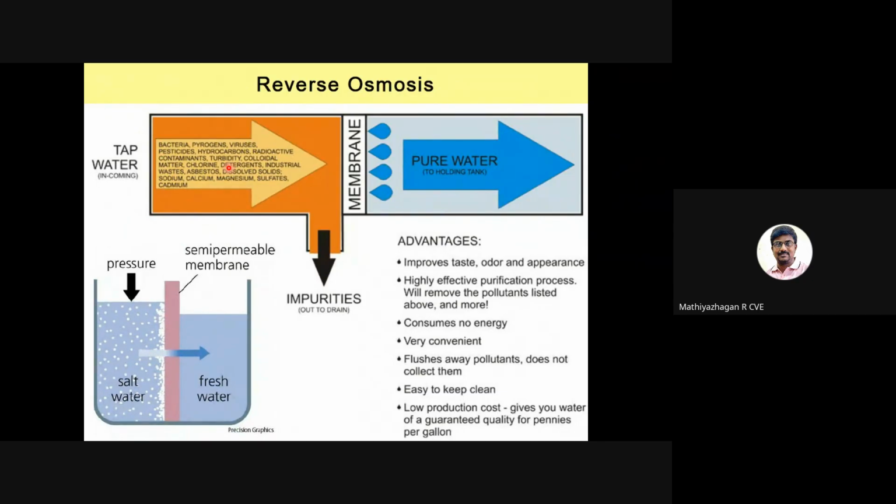For that reason, in our house RO filter also, we have pre-filters outside the filter unit to remove all the sediment and suspended solids, and organic colloidal solids are also removed during the pre-carbon process. So the feed water is free from suspended solids. Only then can we use the membrane for a longer lifespan.